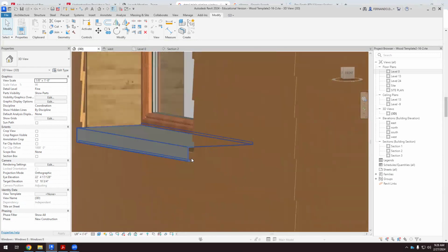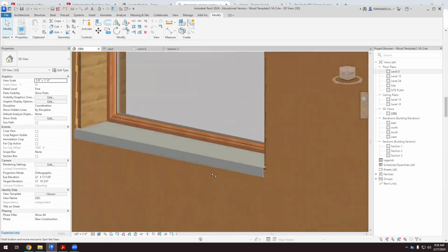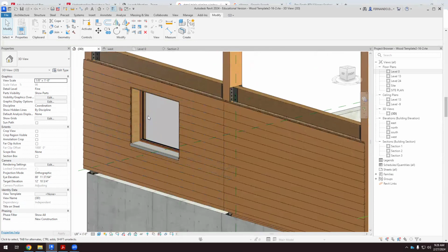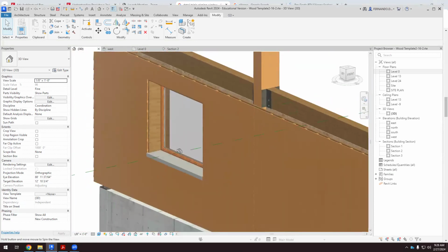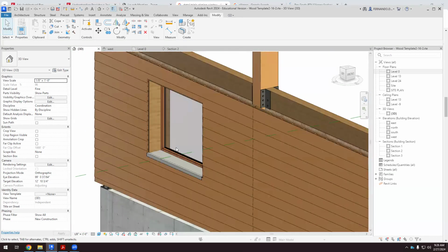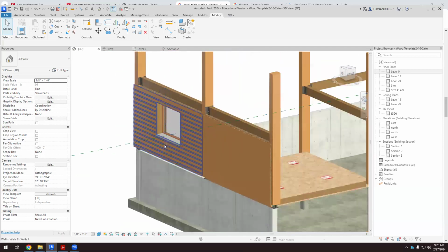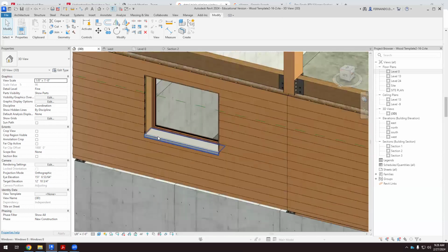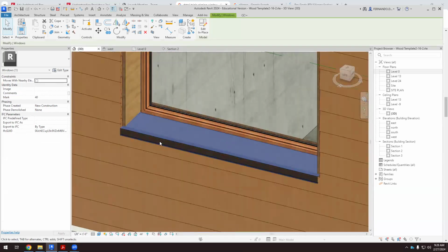Okay, so you see that now we are protecting the siding, and well, we are getting there. So now once we have all these elements, there will be another guy with another big tank of silicone sealing everything around the window. Every single gap has to be sealed with this silicone. This is aluminum.